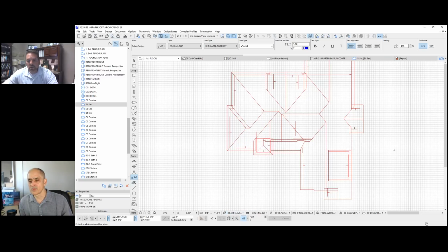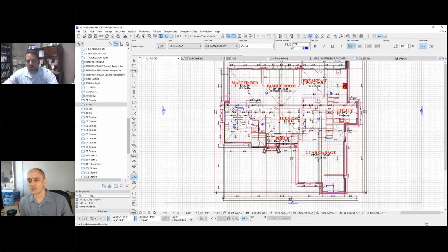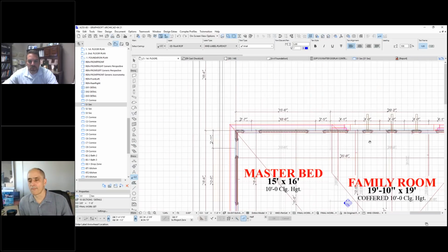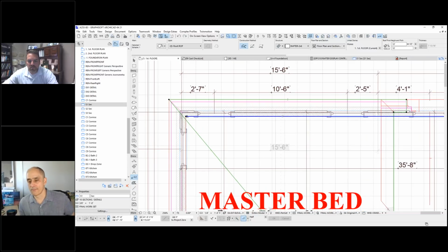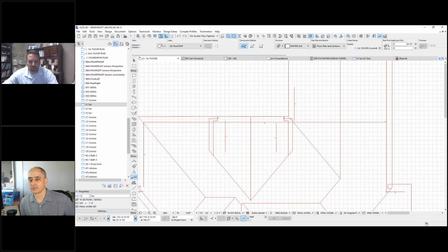Yeah, so the way we pitch all of our roofs is to the inside of that wall. So the roof is here and that pivot line is to the inside of that wall. When you look at it over here, the cleaned up, you can see that these lines are actually pitching here, but this one's very far off because there's a knee wall that this is pitching off of, and it's raking down.